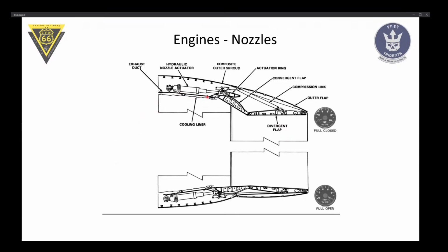And if we would use the same geometry, our gases would be what is called underexpanded, which means they would still have energy to accelerate further downstream as they exit our nozzle, which means that we would have wasted energy that we could potentially use to maximize our thrust. And to prevent this, we have this variable nozzle geometry.